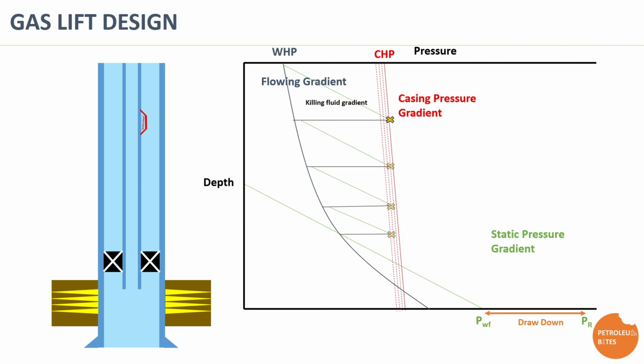This sequence is repeated and continues until the deepest intersection point is reached, where the final valve is kept open as the operating orifice valve to ensure continuous gas injection during production. With that, the total required number of valves is determined along with their downhole depth and operating pressure to obtain the required well production rate.